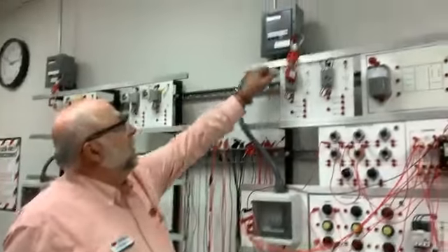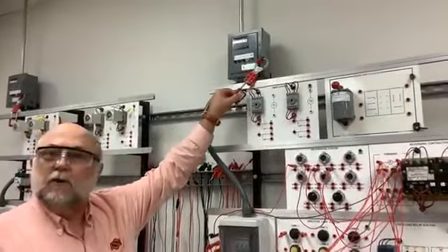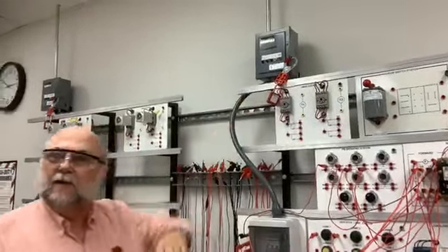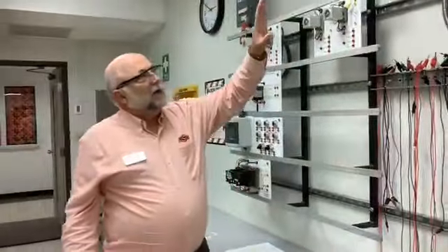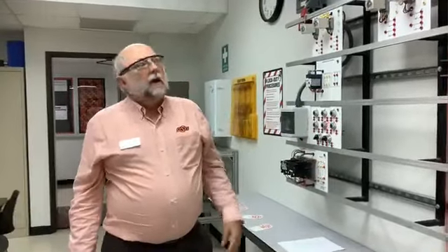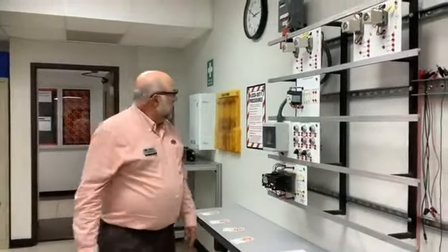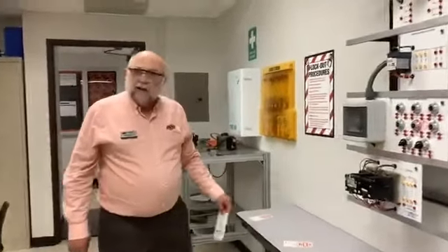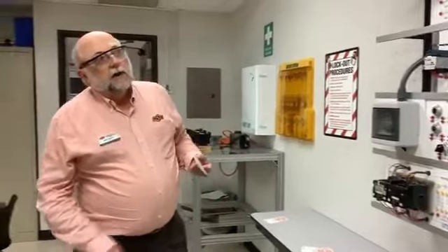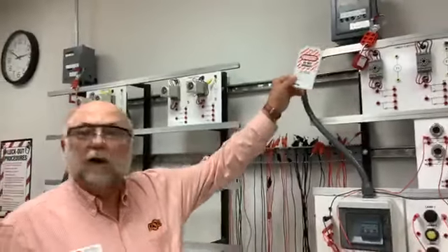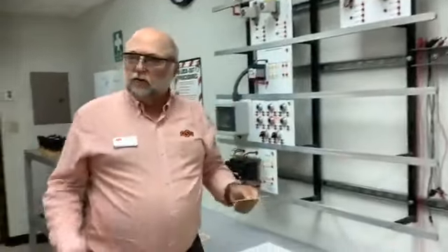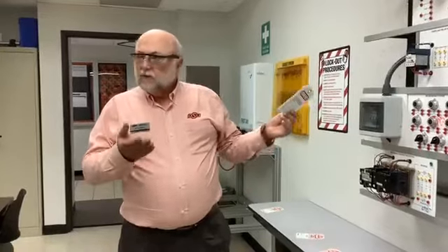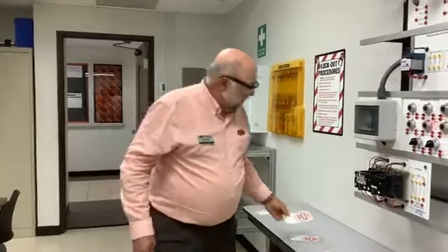It's controlled up here, but we look here, there's no way anyone can actually get into this, right? They cannot actually put power to the circuit unless they have a key to that lock, right? So that's what we call lockout tagout. And what we'll do sometimes out in industry, particularly, we'll not only have a lockout, but then we'll have a tag on here, do not operate, danger, right? Because there may be physical damage or injury, right? If somebody is working on a circuit, okay?